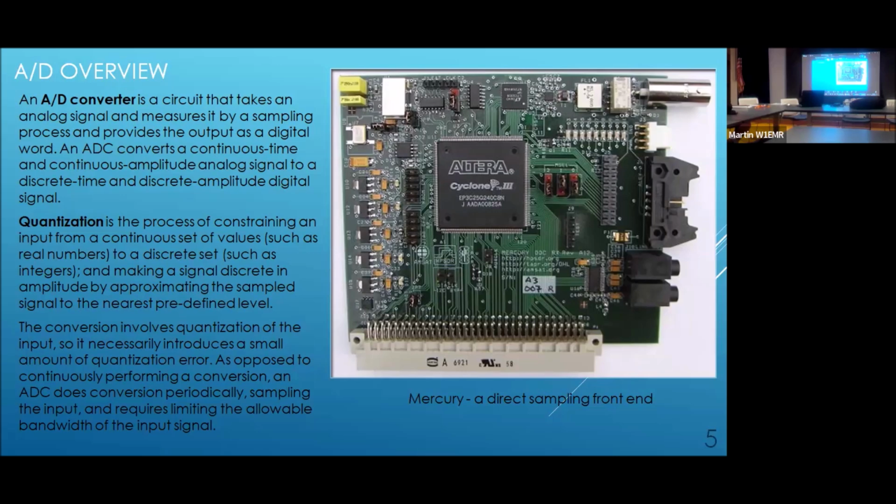And it goes into a mode that they call aliasing, which is sort of like spurious responses out of your mixer. So what we have to do is put a filter in front of the analog to digital converter to minimize the signals that are over frequency. Okay. So it definitely has a limit. All right. And we have to understand what they are in these radios. All right. Next slide, please.